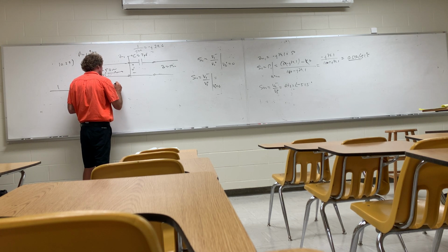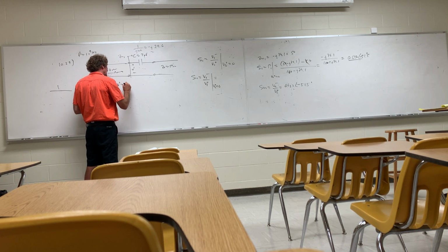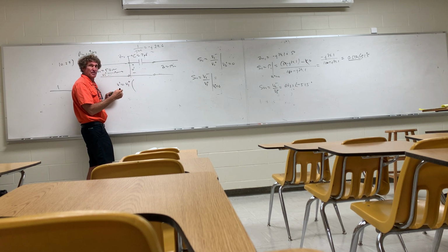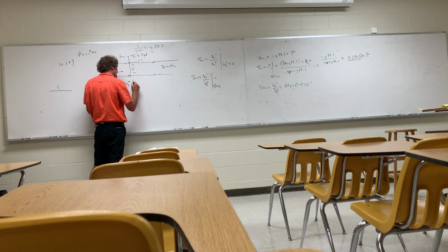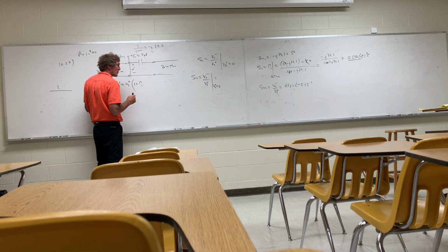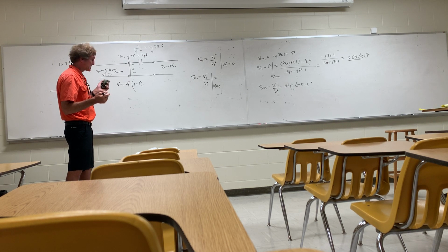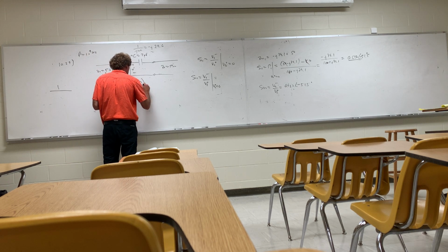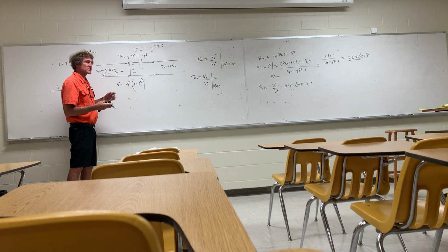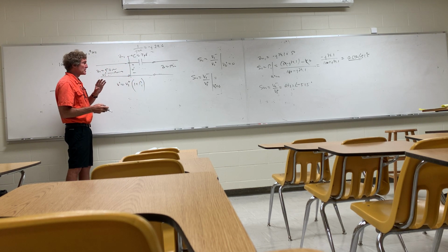I can say my V prime here is V1 plus times the transmission coefficient, right? Well, the transmission coefficient would be 1 plus the reflection coefficient of port 1, wouldn't it? Y'all follow me on this? So that's the transmission coefficient: 1 plus the reflection coefficient. I'm doing this for a reason.